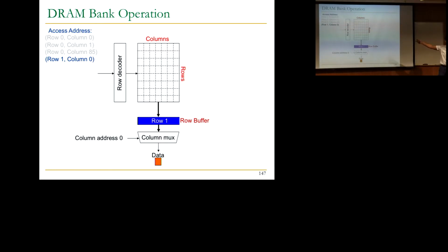We're going to go into the detail of exactly how this works. This is an abstraction, because it's assuming that a bank has a single row buffer. Even that's not true, actually, in the real design. A bank has a single row buffer that's visible to the memory controller today. That might change in the future. How would you choose the size? It's a magic equation. I'm not going to get into that, but I'd be happy to discuss that separately. Okay, but usually this is like a square.